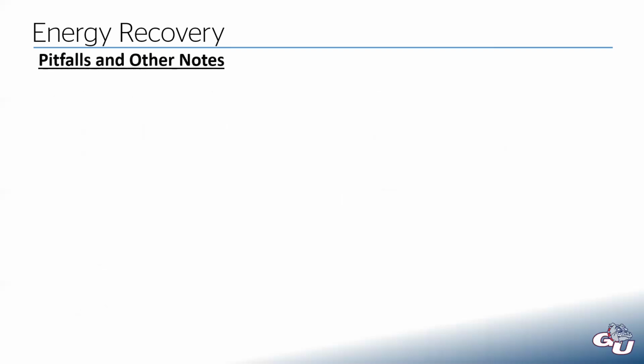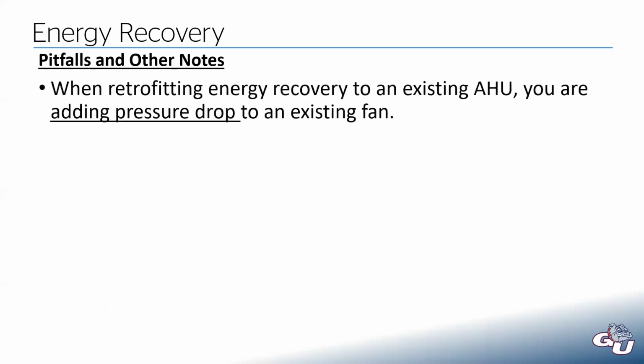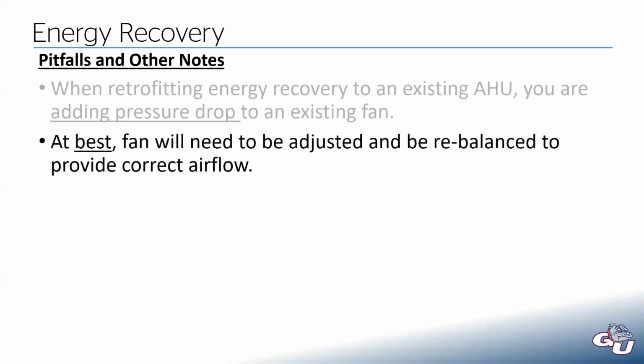So, some pitfalls, some things to watch out for. If you're putting an energy recovery device on an existing air handler, you're adding pressure drop to the existing fan. We already talked about that, and we talked about the energy impact, but also, at best, you're going to have to adjust that fan, and you're going to have to do what's called a rebalancing.